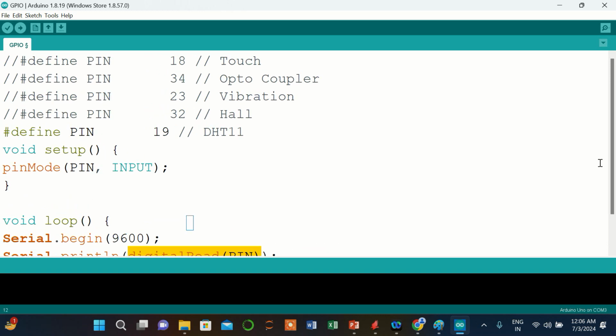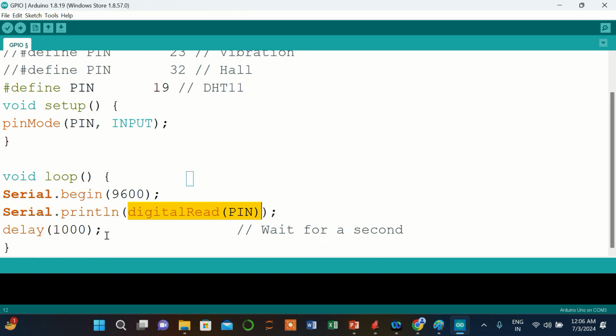And dump it on the serial terminal, with Serial println and delay. So in this loop we'll keep on reading pin number 19 and display it on the computer monitor. This is one way of reading the data from the pin and displaying it on the computer monitor. Anyhow, the microcontroller has a serial port to dump the data. Or if you do not want to use the serial port, let's say you comment this out, just to begin with.